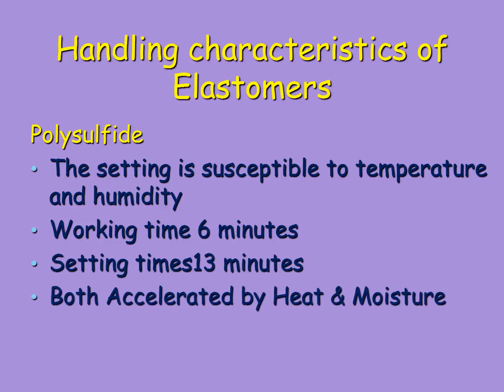The handling characteristics of elastomers. First, the polysulfide. The setting is susceptible to temperature and humidity. The working time is 6 minutes and the setting time is 13 minutes. They are both accelerated by heat and moisture.